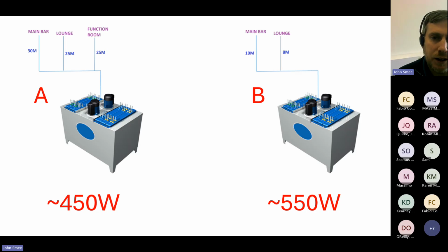But if you go back to your affinity laws, you will see that when the flow rate increases, the impeller speed will slightly increase. A slight increase in impeller speed will result in a significant power input requirement. So that's the reason for it. Lowering your actual resistance here is going to result in more power consumption.